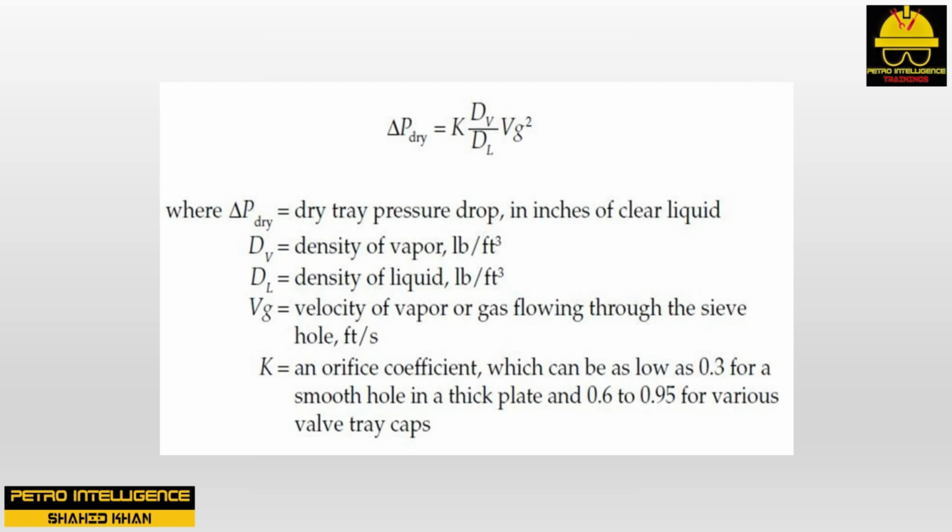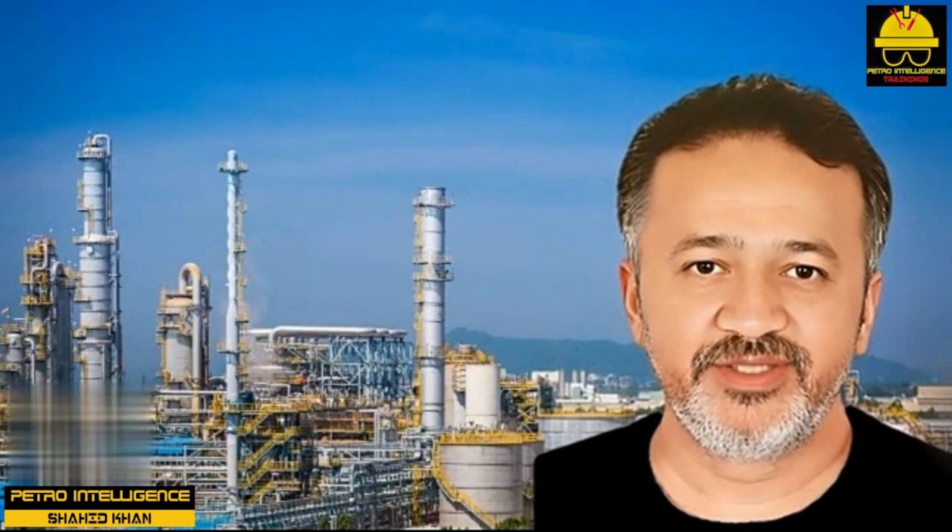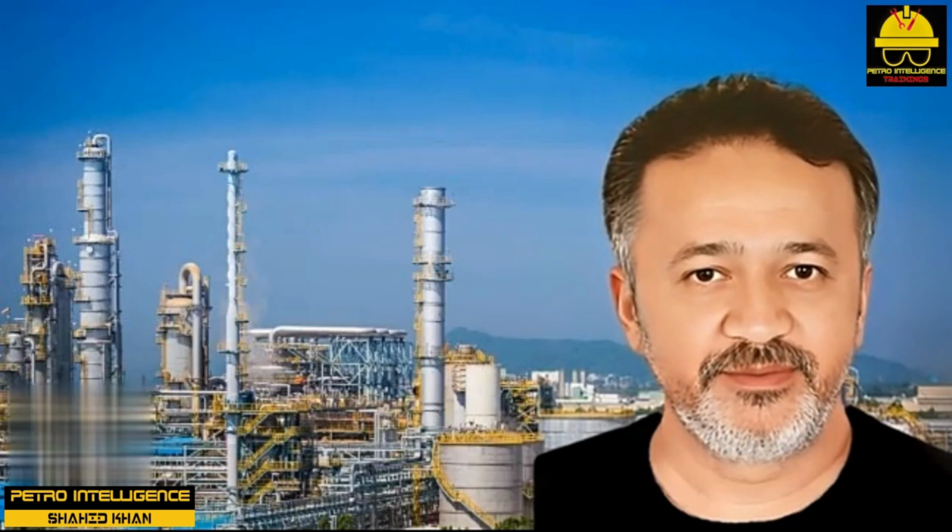ΔP dry = K × dV / dL × Vg², where ΔP dry equals dry tray pressure drop in inches of clear liquid. dV equals density of vapor, pound per feet cube. dL equals density of liquid, pound per feet cube. Vg equals velocity of vapor or gas flowing through the sieve hole, feet per second. K equals an orifice coefficient, which can be as low as 0.3 for a smooth hole in a thick plate and 0.6 to 0.95 for various valve tray caps.